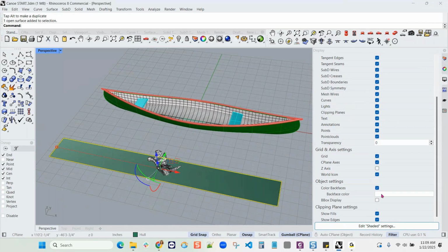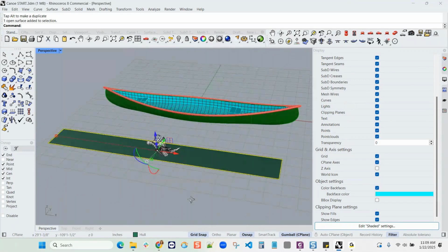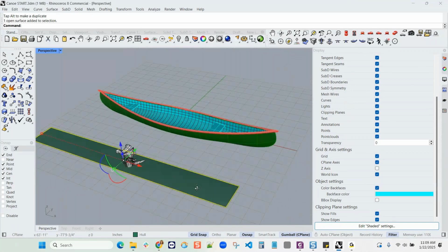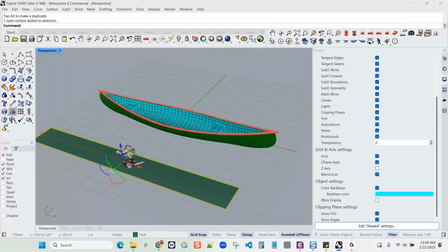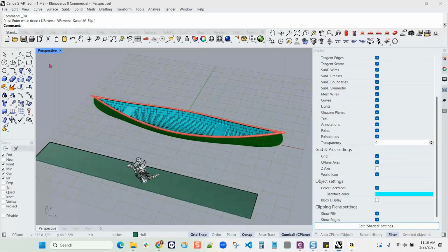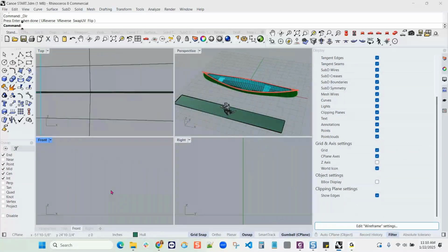If you put the check mark in there, I like making my back faces something bright like cyan. So the top is green, the bottom is cyan. And if I look at the Direction command, that coincides. So direction is positive, pointing up; negative direction is pointing down. And again, that's going to be important.